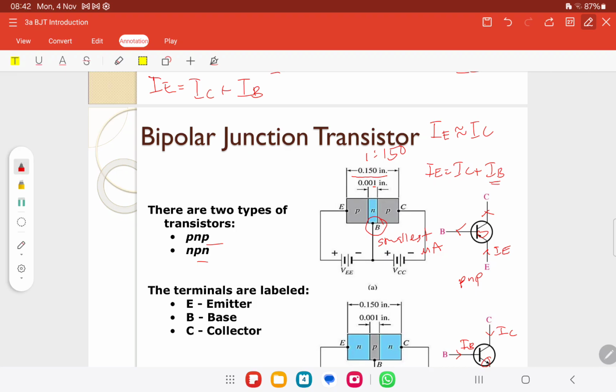Because this one, if it is too small, maybe less than a microampere, we can consider it as 0. But it is not that IE equals IC, it is an approximation. Okay, let's say in calculations we cannot get it either. So you can assume IB is equal to 0, then you can use IC equals to IE. Okay, and one more relationship, IC is equal to beta IB.